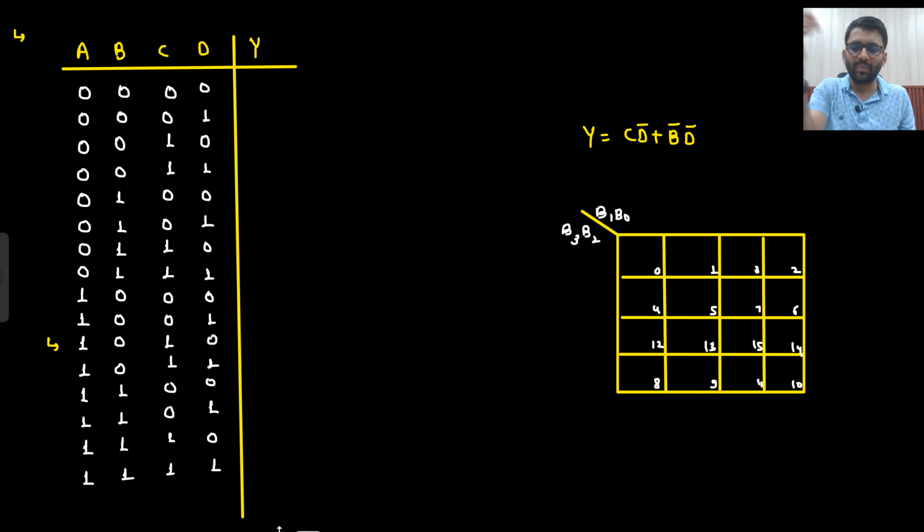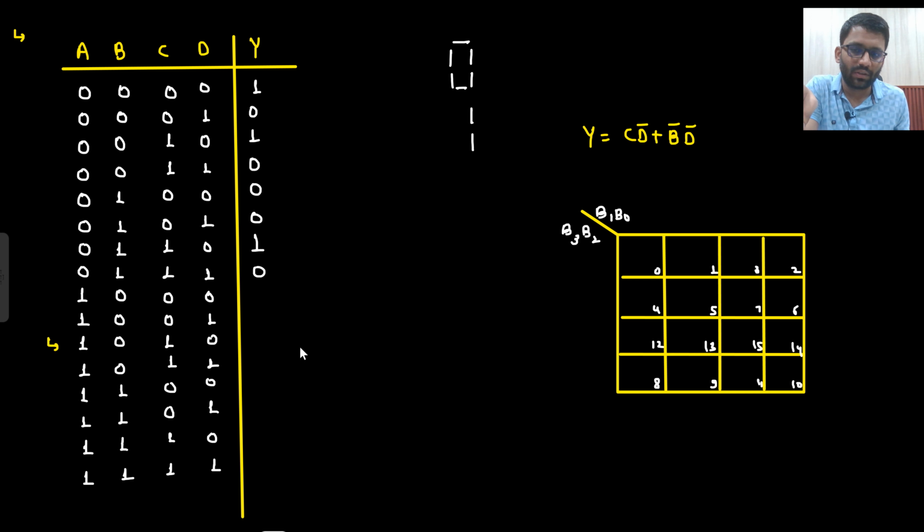So what is my input? It could be 0, 0, 0, 0, right? If it is 0, 0, 0, 0, the decimal equivalent is 0, you should do it on your own first. Is it using? No. If my input is 0, 0, 0, 1, oh sorry, it is using lower left segment, so it would be 1. For 2 it will use, for 3 it will not use, for 4 it will not use, for 5 it will not use, for 6 yes it will use, for 7 it will not use, for 8 it will use, for 9 it will not use.